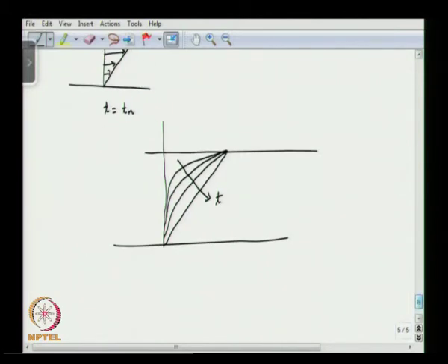So, with that, let us move on and talk about slip flow in case of microchannel flows. So, we will consider Couette flow situation where we will talk about the fluid to be gas. Okay. We know that in case of liquid flows, if the length scale is greater than 10 nanometer, then we can apply the Navier-Stokes equation with no slip boundary condition. Okay.